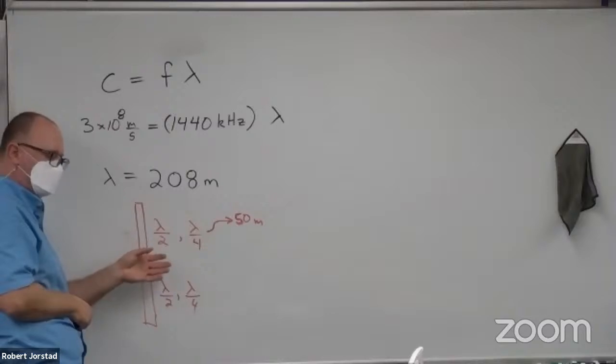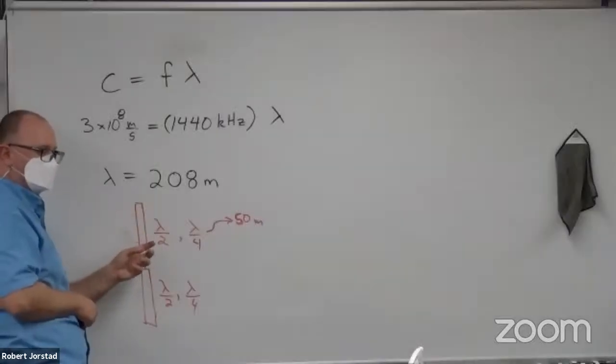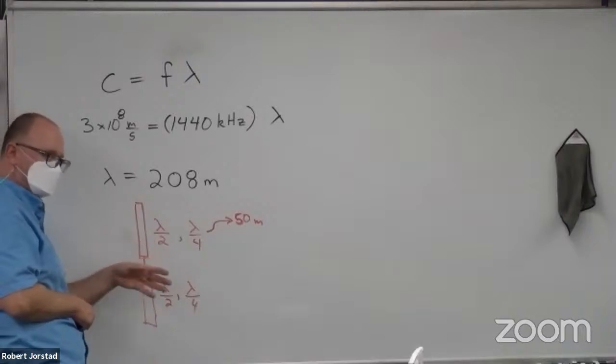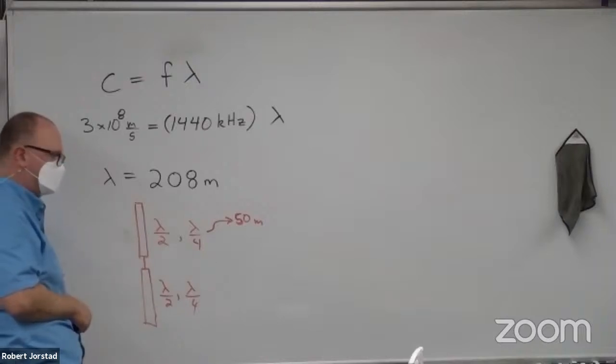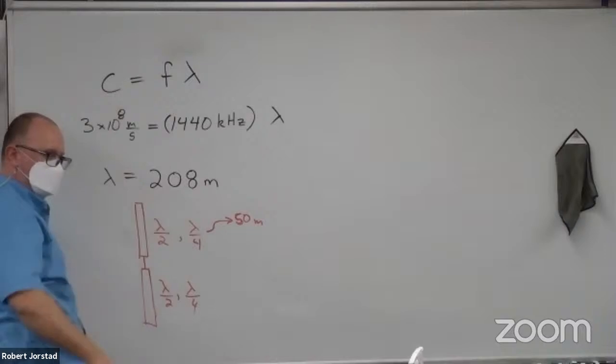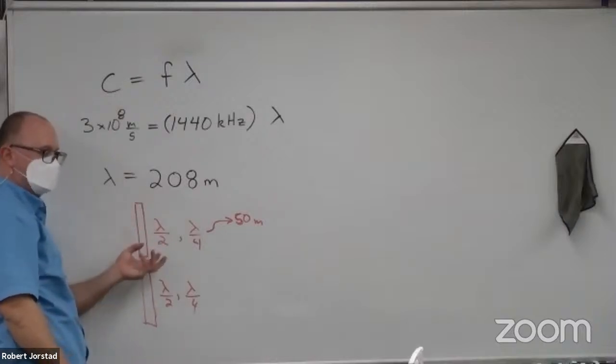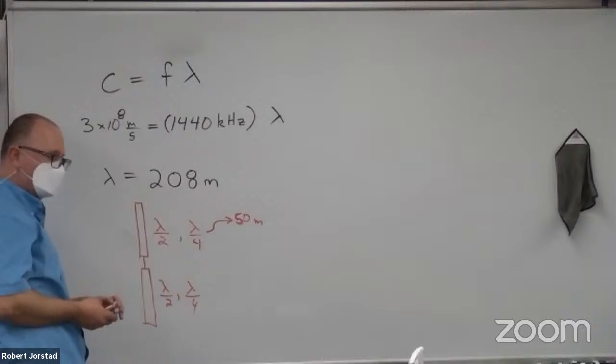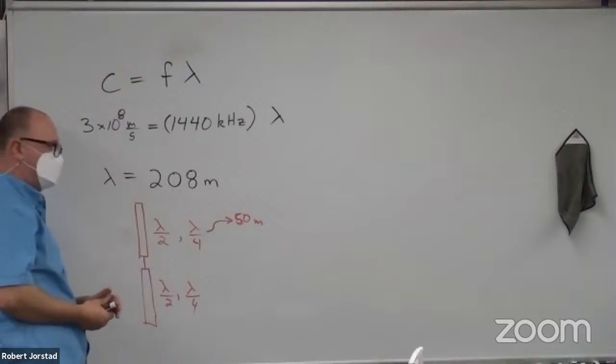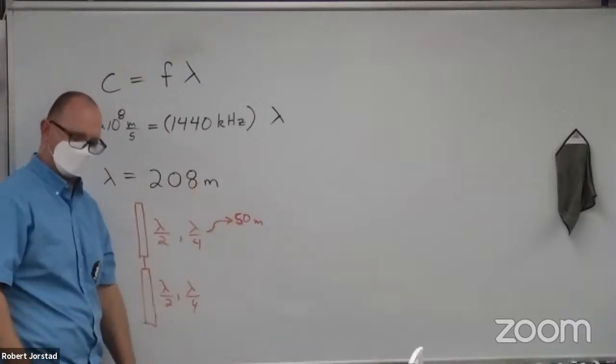Now, why am I bringing this up? Your AM radio on your car clearly doesn't have a 50-meter long antenna, right? But the longer your antenna is, the more efficient it is. And so what we would do is we would take a spool of copper wire and run it between the buildings and try to make sure it was above the ground so people's heads aren't getting chopped off. If you just run a 50-meter long wire, we could totally do that in the lab easy, and just string it along the trees and run out the buildings. And then that makes a huge difference in how effective this is for our cheesy little one. The longer your antenna, the easier it is to pick up these signals. And what we found is when we use the long antenna, it works great.